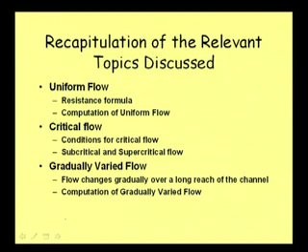We discussed various conditions that we get at critical flow condition. Critical flow itself is a condition, and it corresponds to some very important aspects, that is, the specific energy is minimum at critical flow, or the specific force is minimum at critical flow. Like that we got different conditions. Froude number is 1 at critical flow, all those we got.